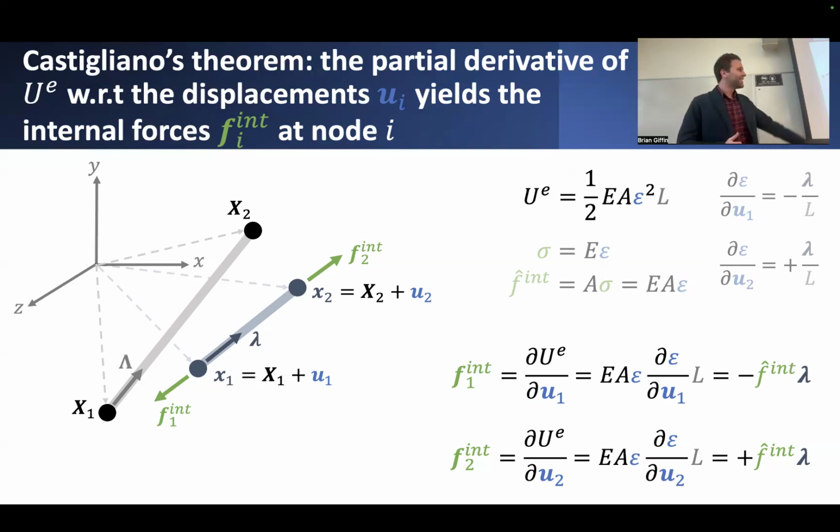It basically says, if we have a truss member, which we assume should only carry axial forces, that is, forces that are strictly aligned with the geometric axis of this member, for that to be the case, we have to define those forces as acting always parallel to the axis of this member, regardless of what orientation it takes, regardless of how much it's rotated or changed in terms of its overall position.